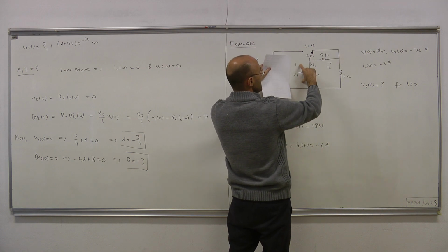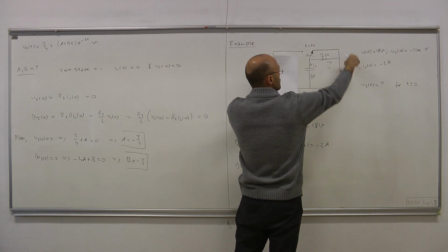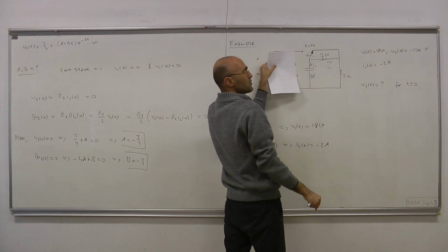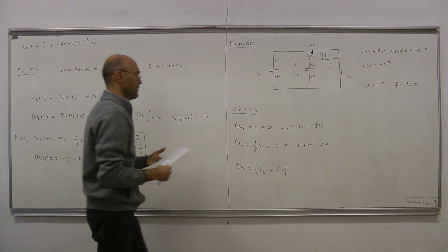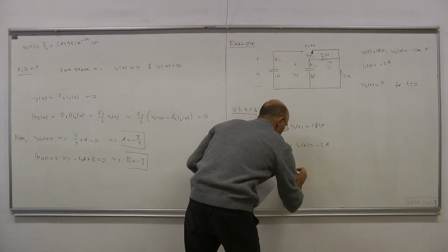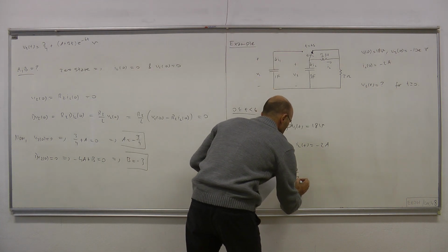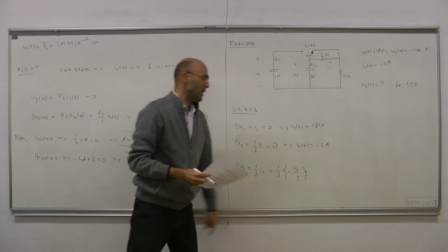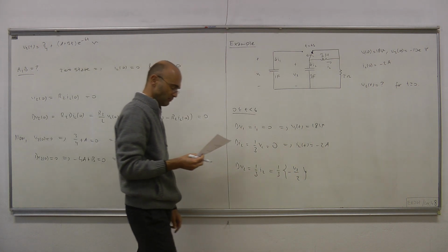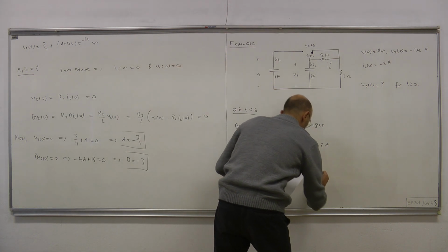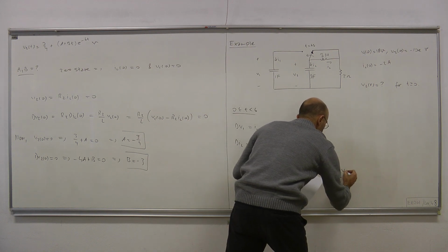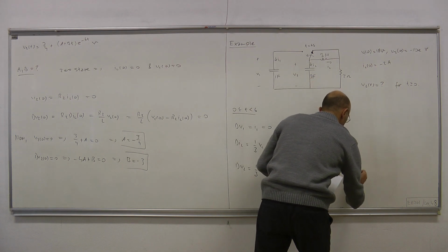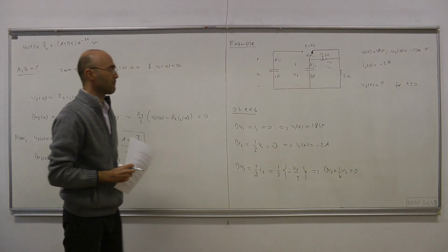Okay. So this is V2, therefore V2 over 2 is resistor current in that direction. Therefore I2 must be minus the resistor current. Resistor current is V2 over 2. Therefore that is minus V2 over 2. Hence we have dV2 plus 1/6 V2 equals 0.